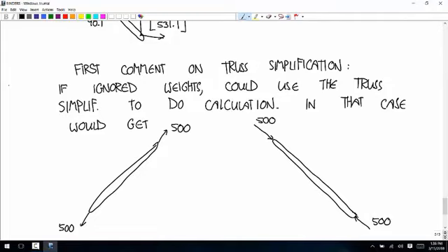And actually that sort of suggests what that truss simplification is based on. The way of calculating trusses that lets you cut out all these equations is based on the idea that if the only forces acting on these members are at the ends, and you're at static equilibrium, then all the forces have to be along the axis of the beam. And if you know the directions of those forces before you go into it, you can cut out a lot of the variables. Instead of two-dimensional unknowns, they're all one-dimensional unknowns. That's what the truss simplification is based on, just sort of loosely.